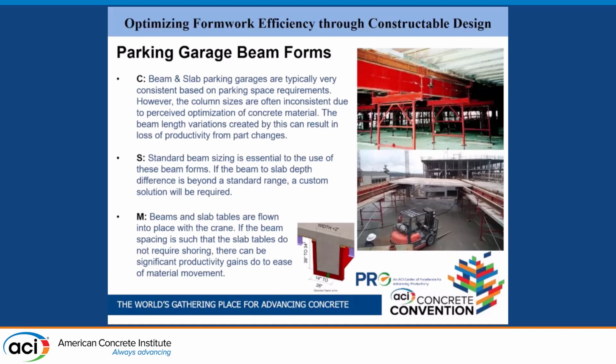Standard beam sizing is essential. Places have these in certain sizes, and we want to stick to those. So knowing what those are and being able to work with your formwork contractor and the designer to say, hey, all right, we need to change our depth a little bit to make this work, that we can do.